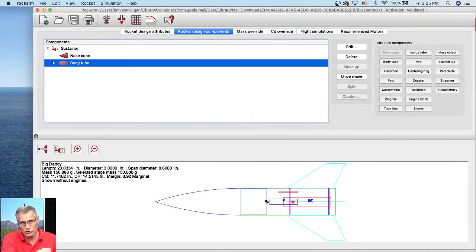What you should do, and this goes for everybody, this is a pre-flight inspection of all your rockets: when you're prepping your rocket, pull on the shock cord, pull hard, stretch it out, pull on both ends, pull on the bottom, pull on the top. Make sure that the rubber is not going to break on that flight. So it's a common pre-flight checklist item to test your shock cords.